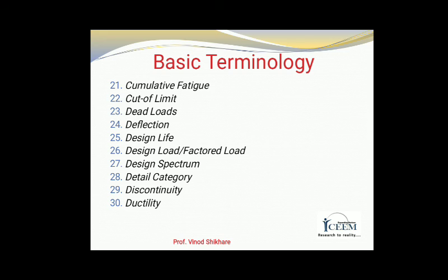Next term is cut-off limit, the stress range corresponding to the particular detail below which cyclic loading need not be considered in cumulative fatigue damage evaluation, corresponding to 10⁸ cycles in most cases.